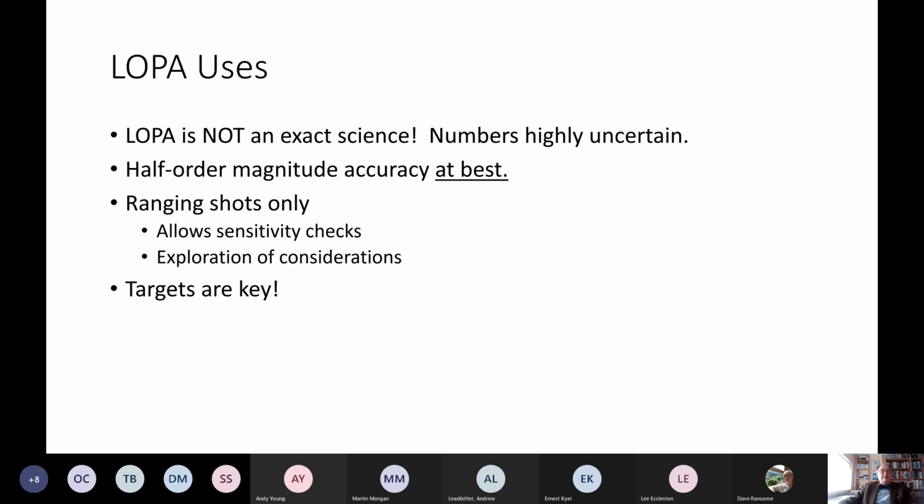Fundamental to all of this, of course, is the actual SIL target that we're trying to achieve. And I could spend a whole presentation just exploring tolerable risk targets and their specification, because it is an area where there is a lot of confusion. One of the first confusions that I often see is that because people have met the broadly acceptable threshold that the HSE point to of 10 to the -6 per year for individual fatality, people assume that that is the appropriate target for a fatal hazard, and that isn't necessarily the case.